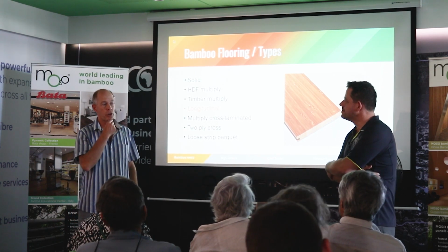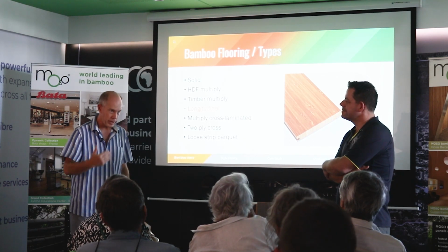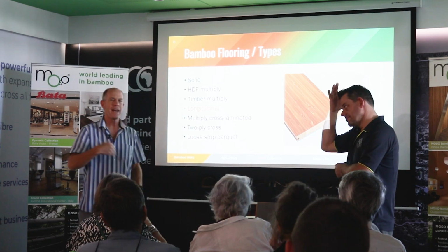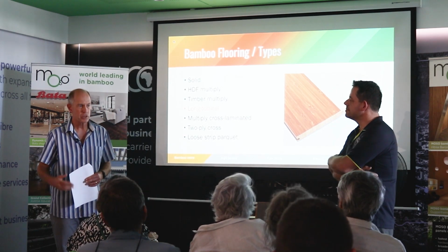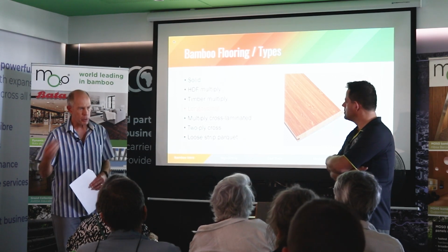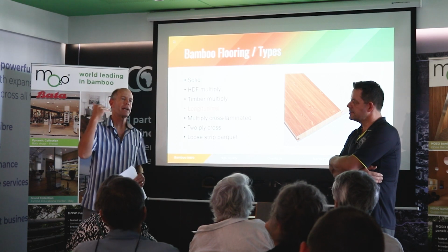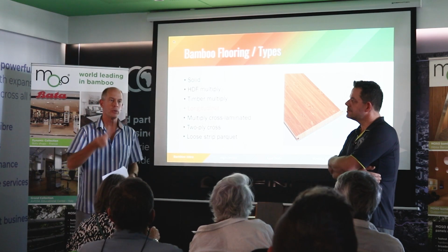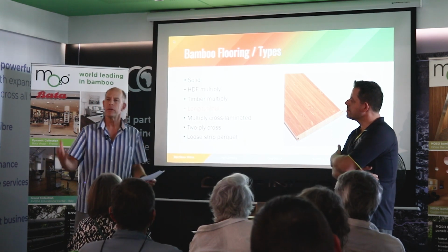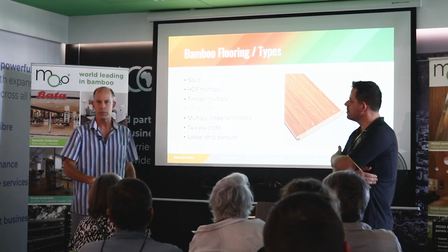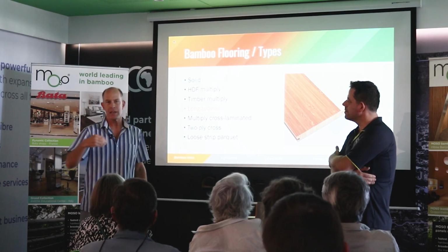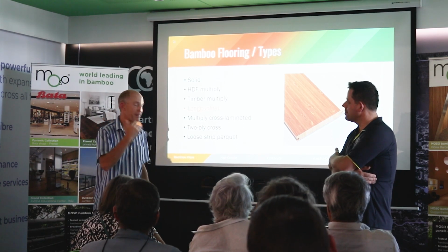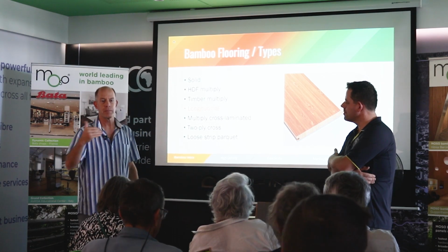One of the other advantages of the longitudinal one is that it's 100% bamboo. Obviously, the timber multiply or the HDF core has some non-bamboo components in it. So for a very strict green building project, if you're going for a green building rating, you probably get a greater number of points for a solid bamboo flooring than one that includes HDF or timber, depending upon where the HDF comes from, whether it's FSC, etc. But there are various hoops to jump through there, but that's one of the 100% bamboo flooring types.